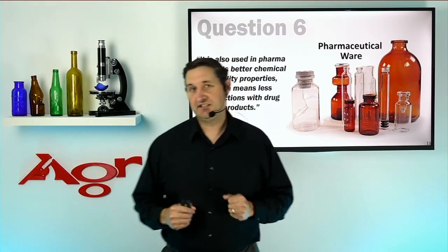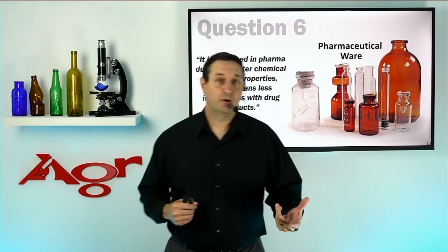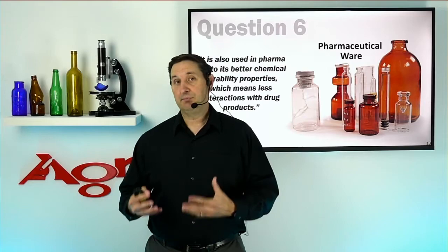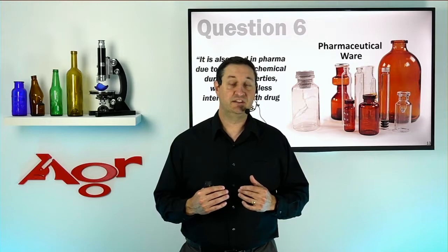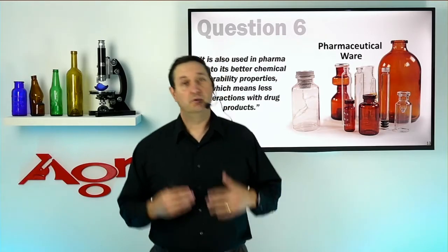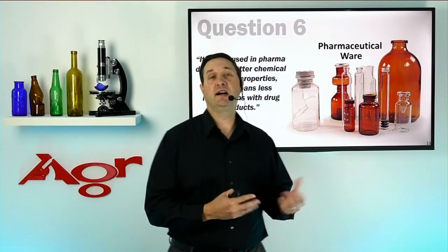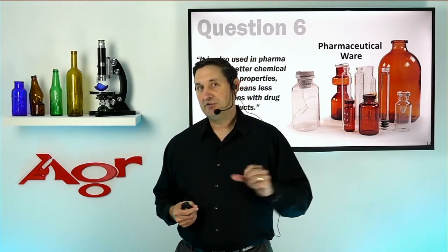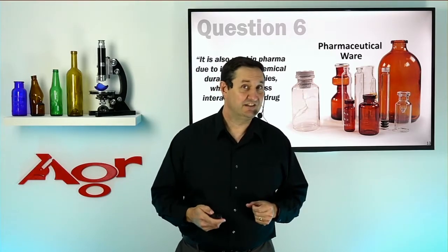Now, borosilicate has its place, of course. We see that when it's in things like pharmaceuticals, because as a pharmaceutical, borosilicate is not reactive with the product, and consequently, that's something that's desirable. We also know that borosilicate has low thermal expansion characteristics compared to soda lime silica. Consequently, we get good thermal expansion resistance. So things like a Pyrex in your labware is great use of borosilicate, or possibly cookware. Those instances, it's justified to have that higher price. But in our everyday soda lime silica containers that we put beverages in, that additional cost is not justified.